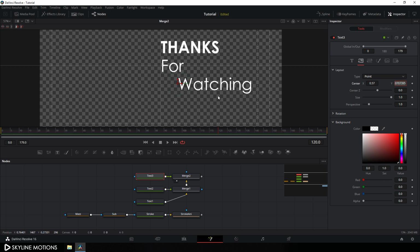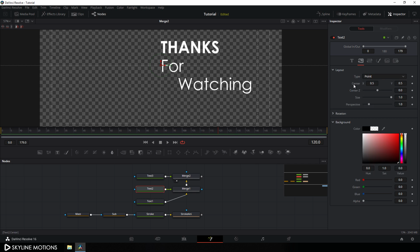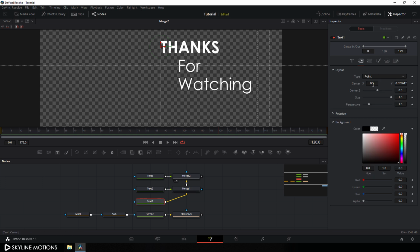Basically I'm going to create a gap from the center. So select this text 2 and put the same value in this. So just go to this layout, and here we have to set this value 0.57, and do the same thing for third one. Go to layout, and here we have to put this value 0.57.